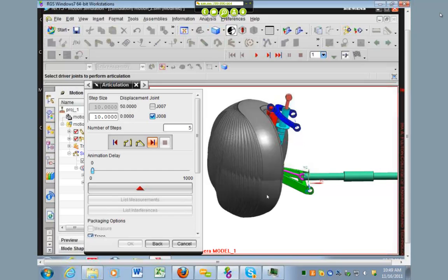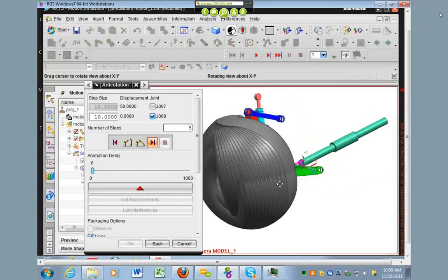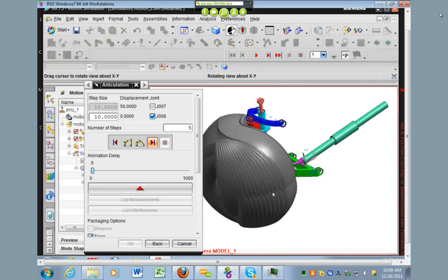So the reason you can do this, at the end of this it says, the trace geometry can be used to establish the size of the fender. The geometry represents the total volume of space required for the tire to operate in the suspension's total range and not touch anything. So that's the purpose of doing this and saving traces, is you can see now how much space this tire is going to take up under the full range of motion.